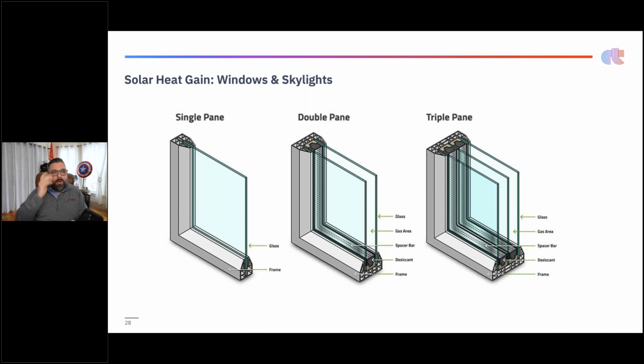So typically a single pane's obvious, you don't need to do this, right? But once you get to double and triple and you get up there in age and you have to wear these glasses, it's tough to see that. It's tough to count the number of panes. That's a real quick, easy trick, and it works whether it's dark or light. Back in the day, we used to use a lighter. Not a good idea. Don't do that. You can burn that glass pretty easy.